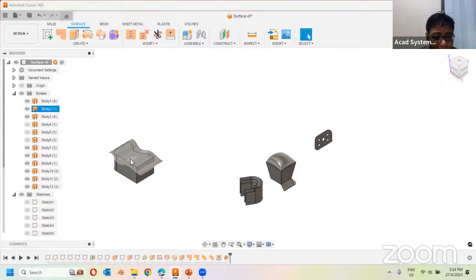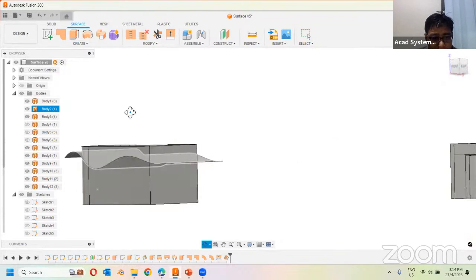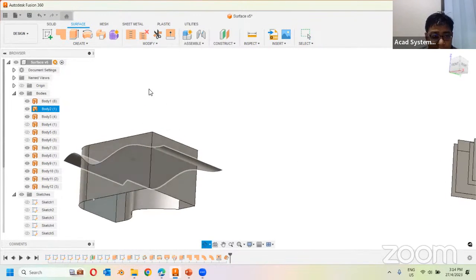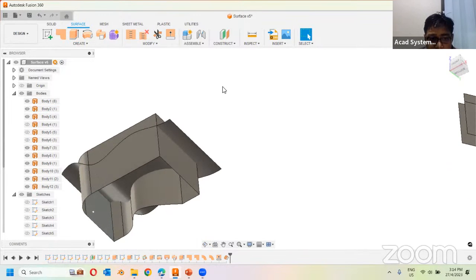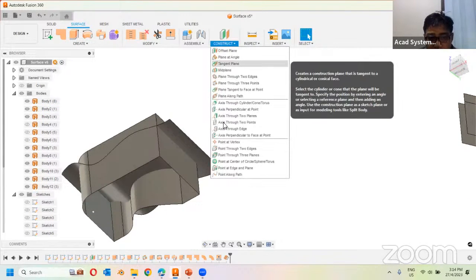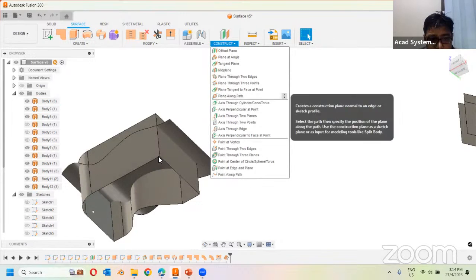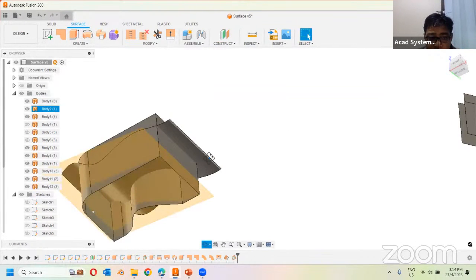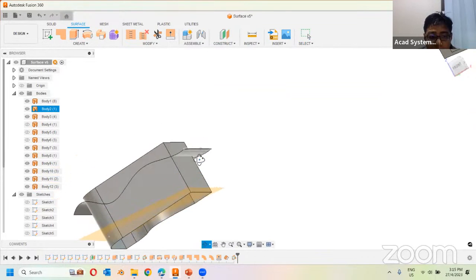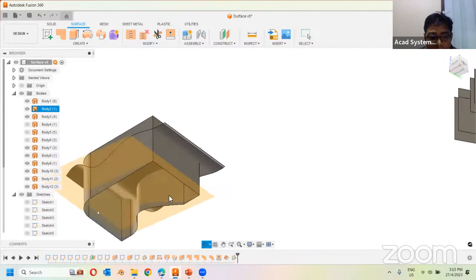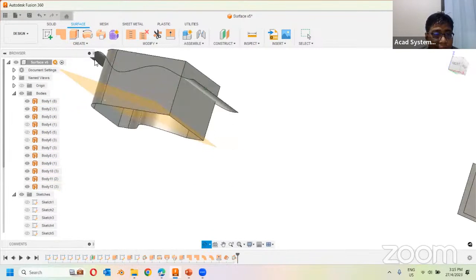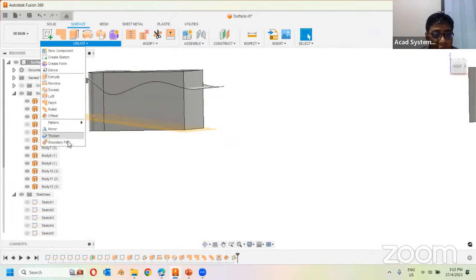I have two solid bodies over here, and they're not quite closed yet. So I'm going to add some construction lines just to make sure that there is an enclosed area inside. So I can select 3 points, let's say from these 2 points, these points. So basically there is some area inside. That area inside can be converted into a solid by using the boundary fill.